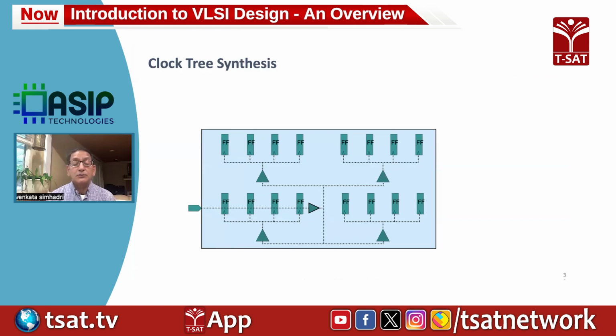And so there are two terms you need to understand here when you're building the clock tree. One is the insertion delay and the clock skew. So basically, the skew refers to the variation of the clock delay between different flops, and you will be learning more about these things in the actual physical design webinar.